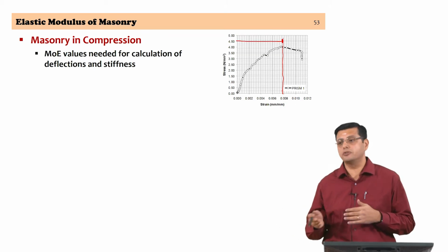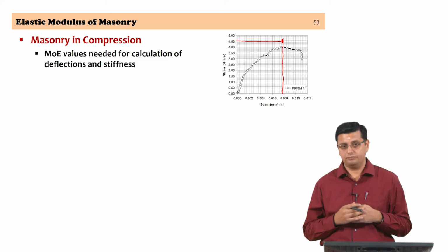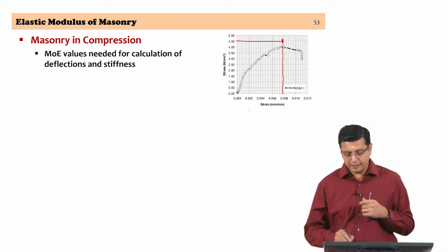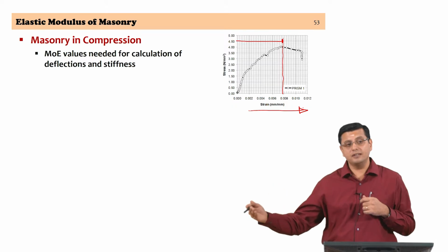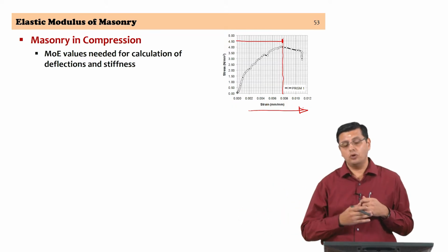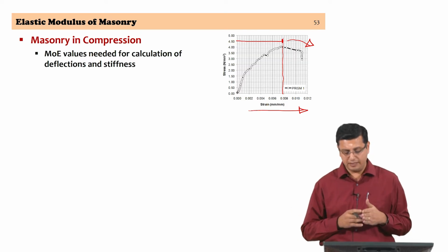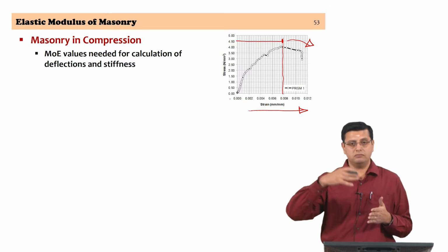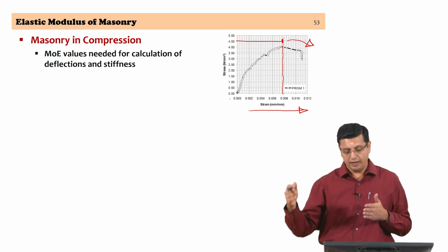and you cannot have a force control test anymore, because you cannot reduce the applied force, the system is not going to respond. Displacement control or strain control tests are where you continue to increase the displacements or the strains, and you get reducing resistances beyond the peak. So, a displacement control test or a strain control test is what is going to give you the entire stress strain curve of the material from initial loading, elastic behavior, pre-peak softening, peak strength, and post peak softening until failure.